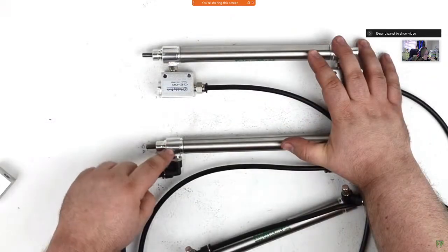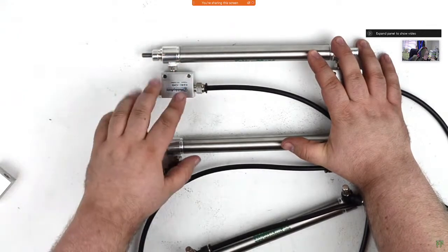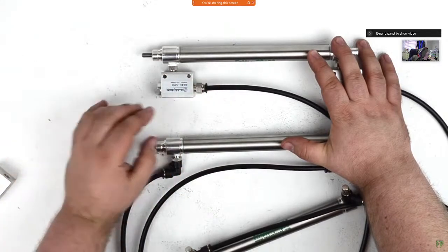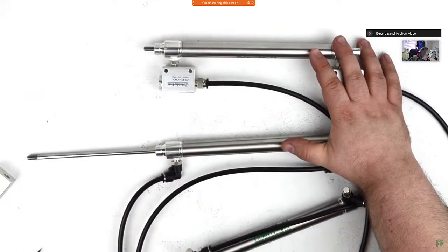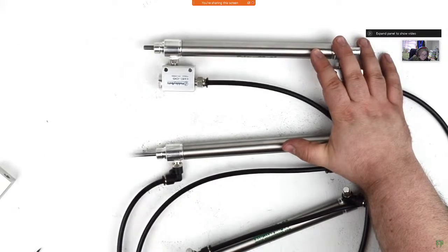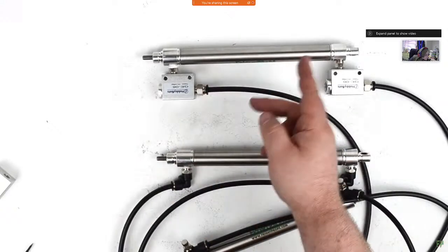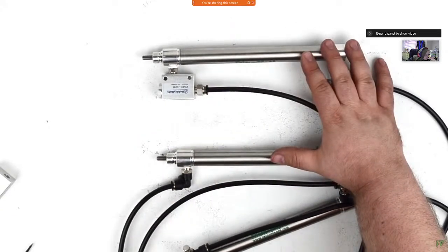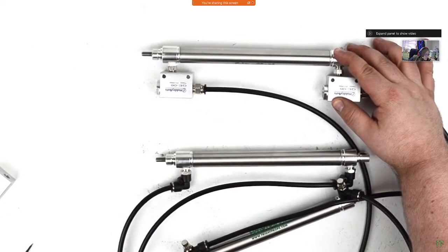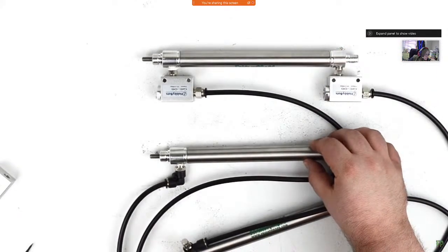Here we can compare a cylinder that has no quick exhaust valves with one that does. And this cylinder stroke is only about 6 inches, so it's not as noticeable, but when you get up to much longer strokes, it's much more noticeable. It's also possible to much more quickly extend and retract the cylinder rapidly with the quick exhaust valves. For instance, you can create a program where the cylinder very quickly moves in and out.